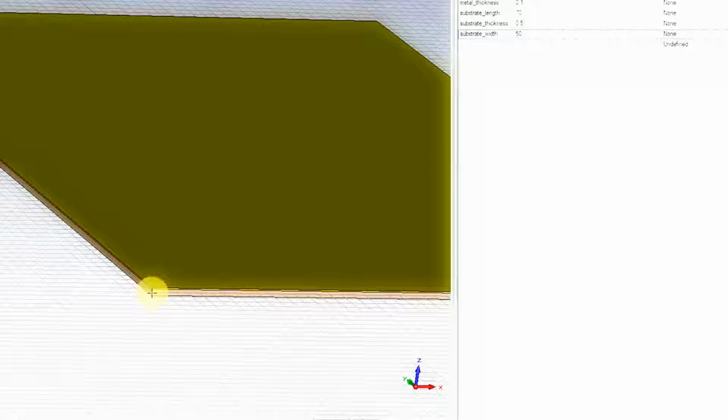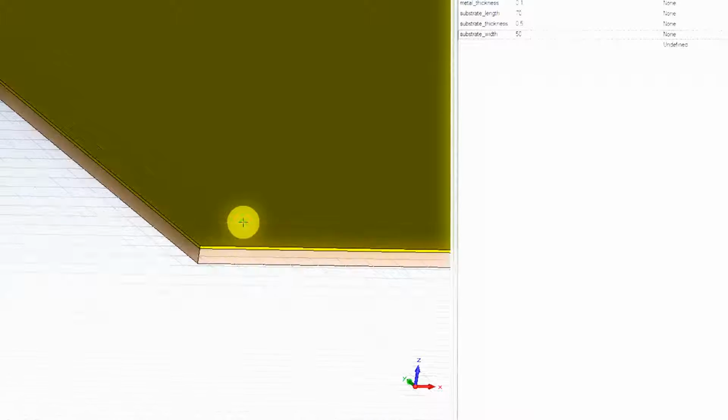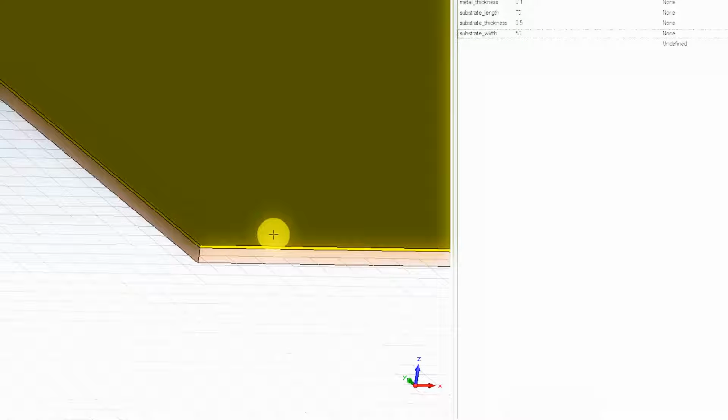Now, as you can see, as I have changed the value, so if I change the substrate thickness back to say 0.5, some values have been modified. Press Home, Edit, Parametric Update or F7. If I just hit the F7 key, it reads through the parameter list again and rebuilds the model, so it makes it thicker as well. That is one of the reasons why parameterizing your 3D models is always a good idea, because you can easily modify them so that you can simulate various different values.